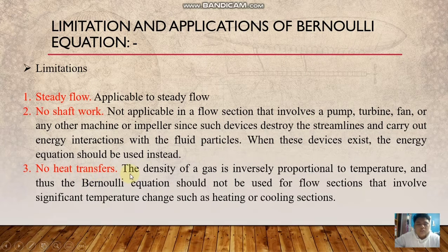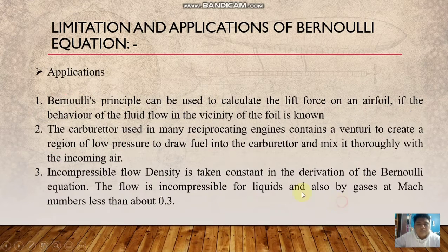Next is no heat transfer. The density of a gas is inversely proportional to temperature, and thus the Bernoulli equation should not be used for flow sections that involve significant temperature change, such as heating or cooling sections.